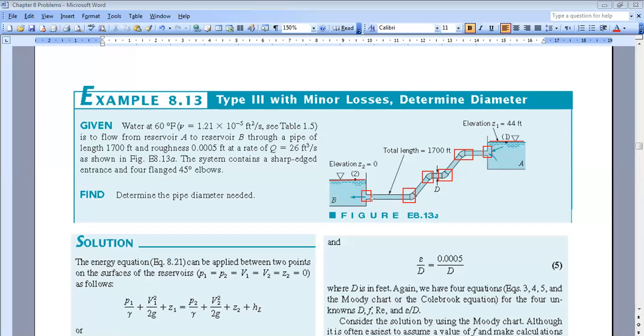Okay, now how to get the coefficient of minor losses? Sometimes they give it to you directly in the given. If not, then you should go to your tables in the book. I will do a summary for you for chapter 8. I will put for you in a sheet the main figures you use, the Moody charts, the tables, the figures used for fittings. And I will put the main relations also as a summary. So here, let us see together how to find them.